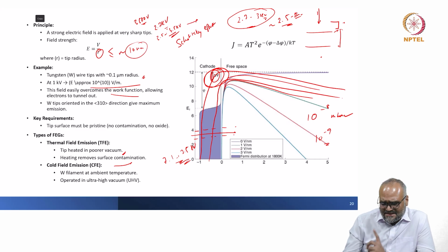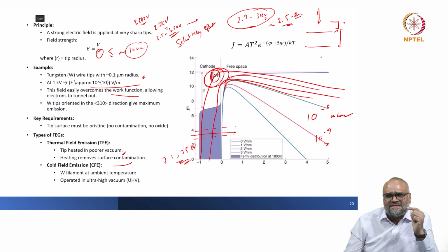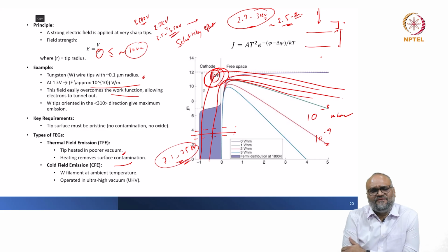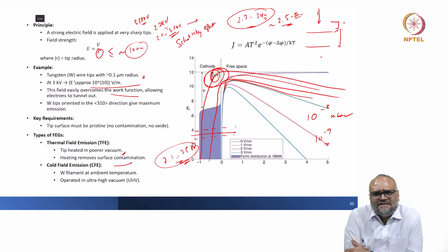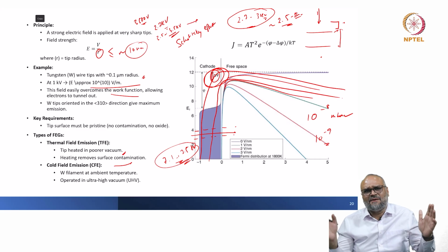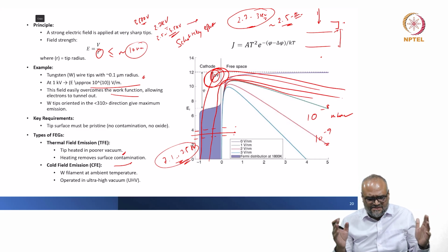Now, the challenge here is the vacuum. Although they are ultra high vacuum, when you go to these high potentials, if you do not have good feedback control, the filament tip can get fractured much more easily. And so the stability of a cold field emitter was not extremely good from the mid 90s to, let us say, the digitization that happened around 2000 or 2005.